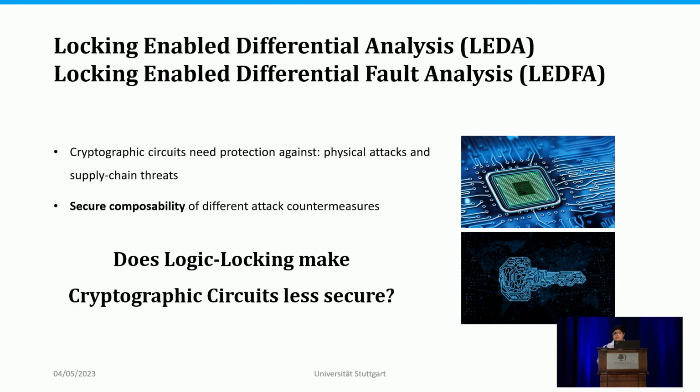That is, whether protecting our circuits against one kind of attack is making them more vulnerable against another kind of attack. In this work, we studied the consequences of applying logic locking to cryptographic hardware, and we introduced two types of attacks, locking-enabled differential analysis, LEDA, and locking-enabled differential fault analysis, LEDFA, which is basically just fault-assisted LEDA.